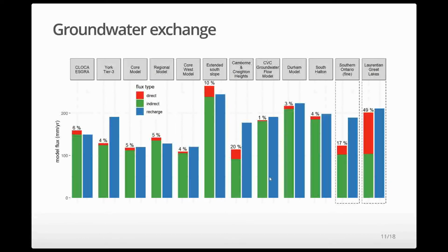They are all a bit on the lower end between that 100 and 200 millimeters, which is indicative of slow flow not being entirely composed of groundwater discharge. They could be from the wetlands and stormwater ponds that I spoke to earlier. But more importantly, we see that 1 to 5 to 10, maybe 20% of that groundwater discharge is coming from direct sources, so along that shoreline.